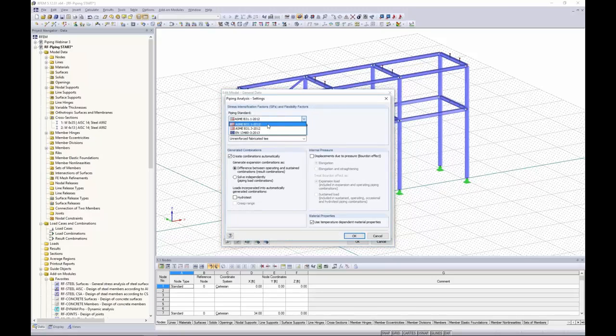The first one is to define which standard we'd like to use. We have the ASME B31.1, B31.3, and recently added is the Eurocode. This checkbox down below is for welded forged T and welded-in contour inserts. This just refers to a couple of variables, RX and TC, that we won't be using today, but just keep that in mind if you are using those types of components.